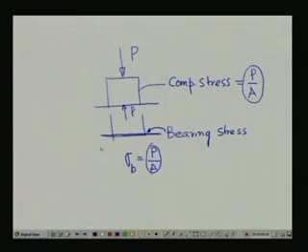Please note that we call it bearing stress only where contact takes place between two different machine elements, whereas compressive stress is an internal stress. So here lies the difference between compressive stress and bearing stress, although in certain cases the expressions for the stresses might look the same.